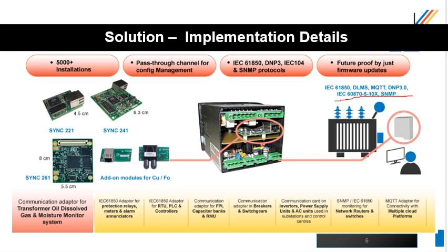So this is the indication of a transformer, and its monitoring equipment is shown by the side here, and this is sent to an analysis system. So this is the overview. This system earlier had a primitive protocol like Modbus. So what they did is they took the unit out, and they wanted to upgrade it to the latest protocols like 61850, DNP3, 104, etc.